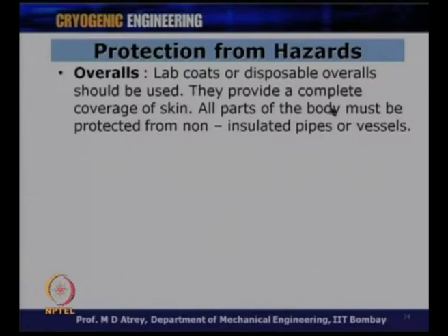Alright, they provide complete coverage of skin. It ensures that nothing is exposed to such low temperatures or cryogens. All parts of the body must be protected from non-insulated pipes or vessels. One should also ensure that you are protected from non-insulated pipes or vessels, and therefore the goggles, the shoes, the gloves and the overalls are very, very important while dealing with cryogens.